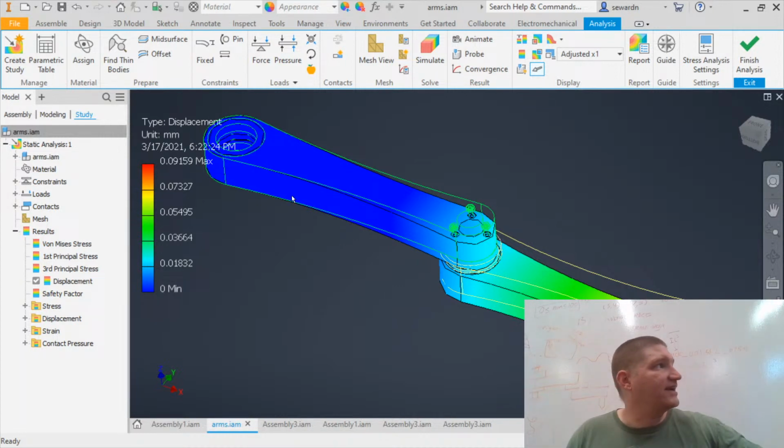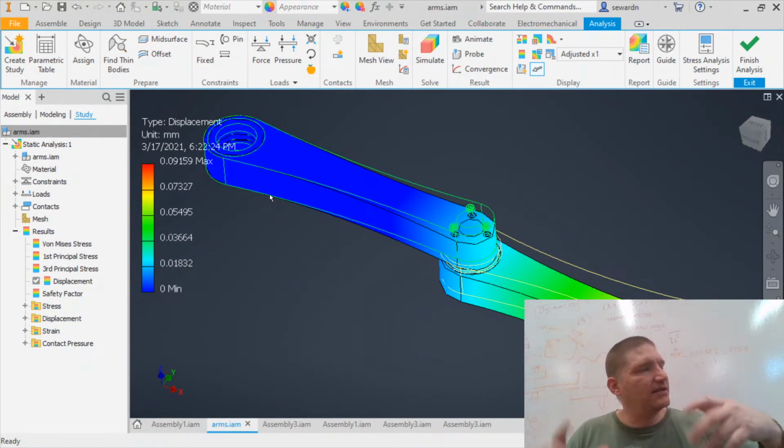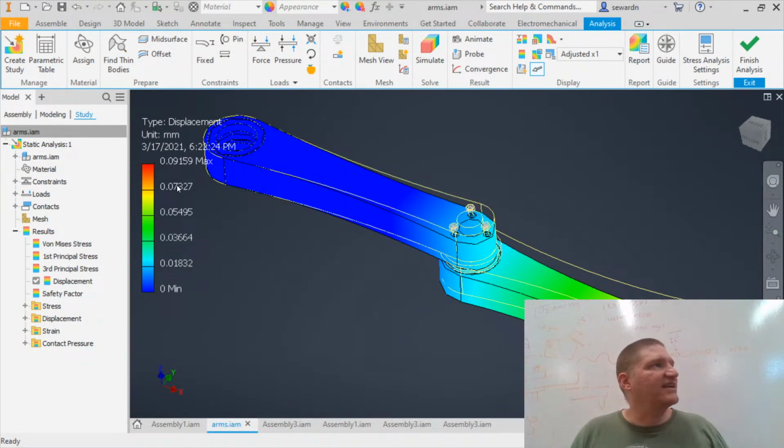So anyways, whenever I actually did the actual test, use your words, Nick. So whenever I did this with a shelled out part, I got about half to 1 millimeter, I forget, with loads bigger than what I would expect. So I think with loads that I was expecting to have, like static loads, not dynamic loads, I would expect to get about 1/10 of a millimeter, which is pretty good. Maybe I'm missing something, very possible.